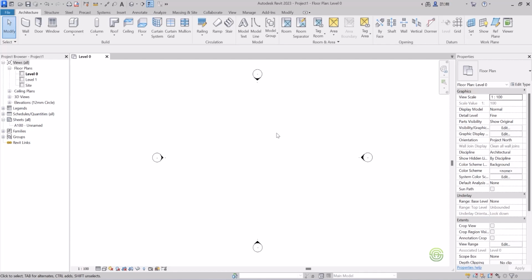Or else it will create some errors in here also. So we should delete the unnecessary layers and unnecessary lines and import only what is necessary into the Revit file. These are the important things, guys, before importing a CAD file.